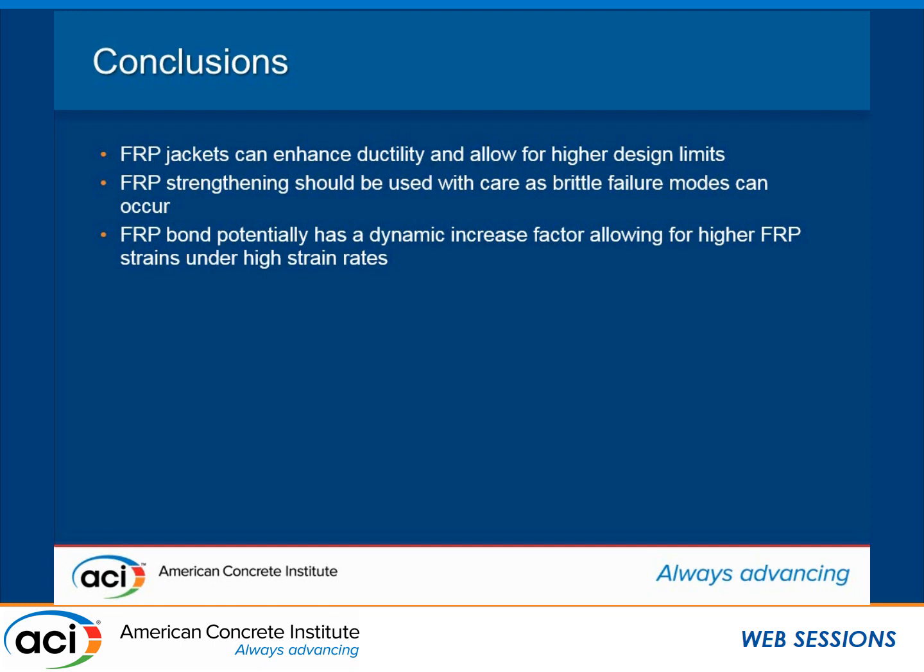For these columns, I used a 10 millimeter aggregate because they were somewhat smaller and there wasn't as much cover distance, and I wanted the aggregate to go everywhere. So 10 millimeters is 3/8 or so. All right, very good. Thank you. Thank you.